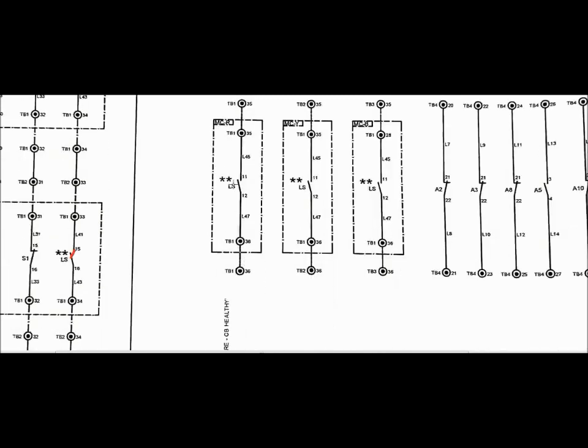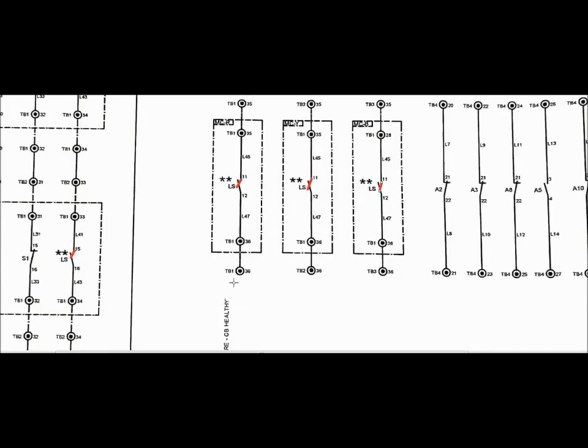These are the contacts taken to the remote end spring charge. Whenever the spring is charged, this contact will be in NC position. Now a DC is taken from the remote end via cable to the TB1 36, TB2 36 for yellow phase, and TB3 36 for blue phase, and from the terminals TB1 35, TB2 35, and TB3 35 taken to the LED of the control and relay panel.